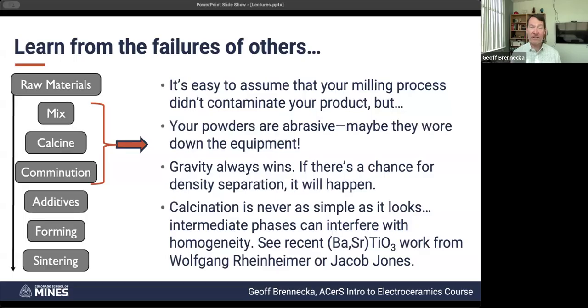So if there's a chance for density separation, it will happen, whether that's milling, whether that's drying, whatever it is. Your powders are just naturally going to separate based on density and based on particle size. And if you pretend that it doesn't happen, it will probably come back to bite you. If you recognize it, it's relatively easy to deal with. And this last one is really important, because as Shannon reminded us, the distribution of different phases in a material can have a big impact on the electrical properties.